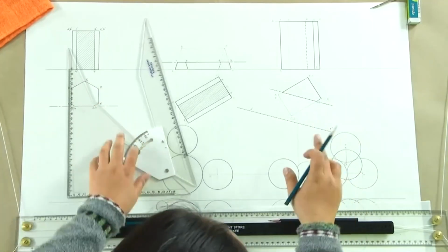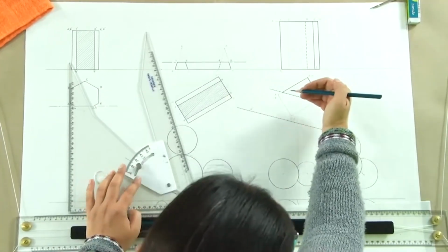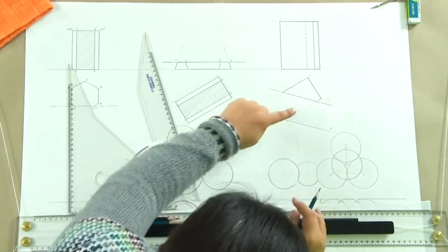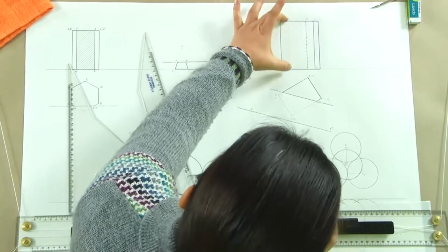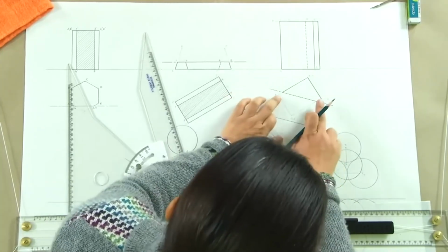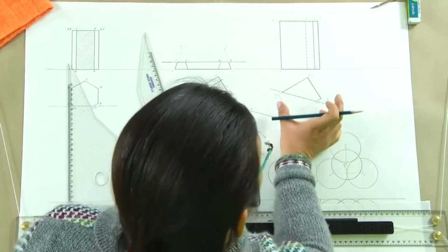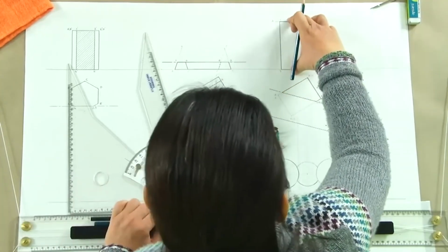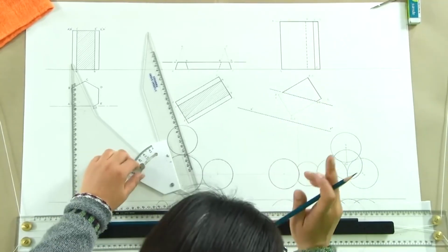Now, what we need is another dimension which is the height. Since this plane is perpendicular to HP, what we will be seeing in VP will actually be the true height. So, the only thing which changes is, since it is making an angle with VP, the horizontal trace is going to be slightly different, but the vertical trace in height is going to remain the same. So, what we will do?